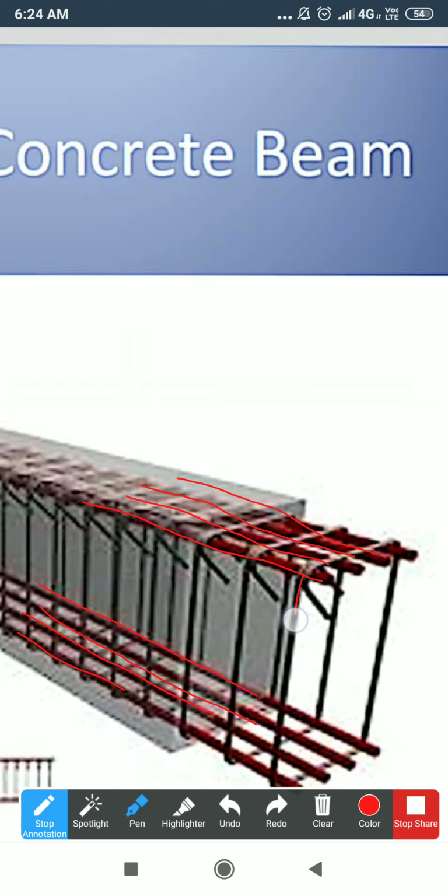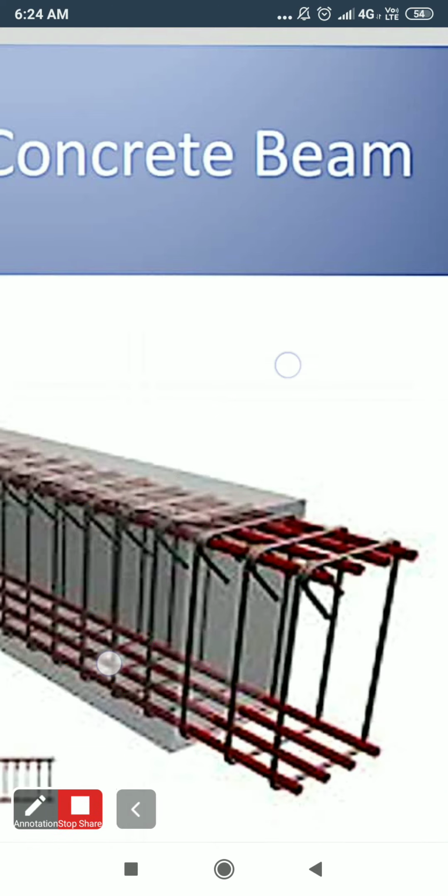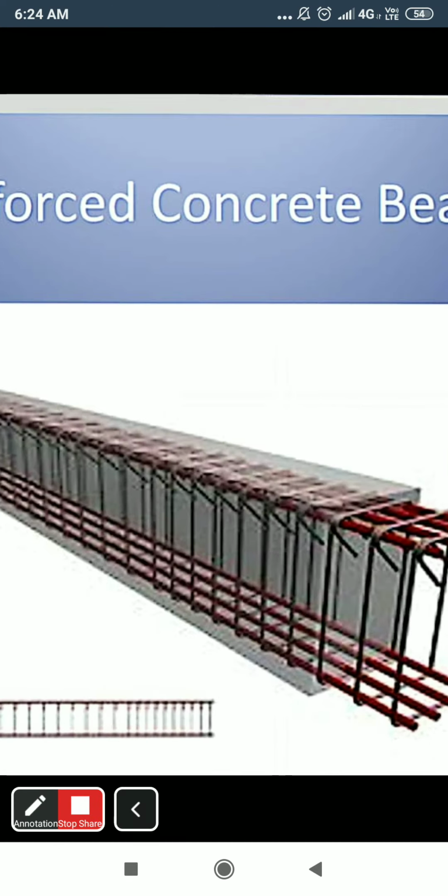See, this is referred to as two leg. This is one leg, this is one. Normally it will be wrapped around the longitudinal bars. This is an example of the two-legged stirrups. So let us come to the two-dimensional view. You start from one end, take it around the longitudinal bars in both top and bottom face, and you have to connect it carefully. The representation is normally in two dimensions.